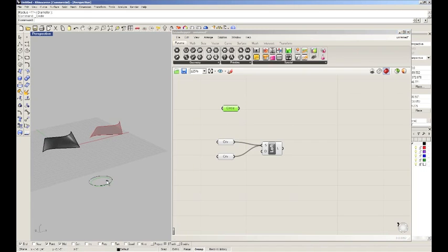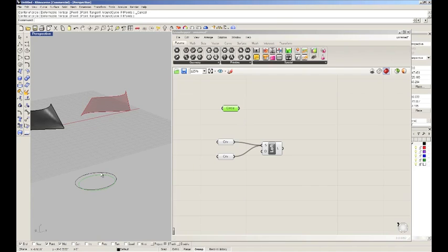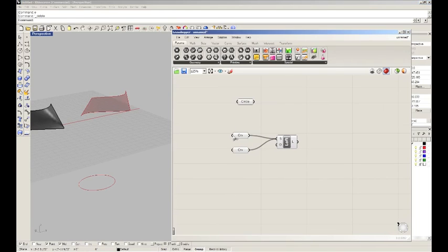And the corresponding object in Rhino, and I'm just going to delete this original circle that I had drawn. So this is the one that I drew when it asked me to set one circle in Grasshopper. The corresponding geometry between Rhino and Grasshopper will be the same color, right? So I select this, it turns green. I deselect it, it turns red. So any Grasshopper geometry in Rhino's viewport, being visualized in Rhino, will be red. And we'll talk about that in a second as well. So orange means it needs information, light gray means it has information and everything is working.